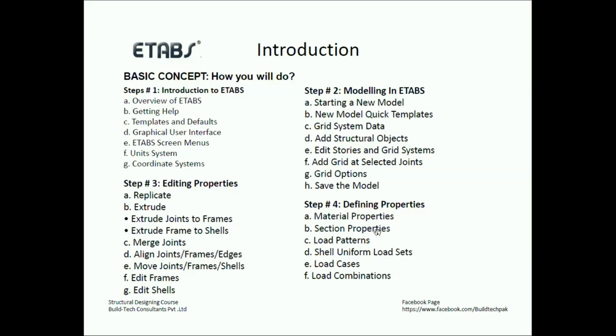Then once it is done, go for sectional properties. Sectional properties mean you will define some trial sections. Then once it's been done, there are load patterns and load combinations.